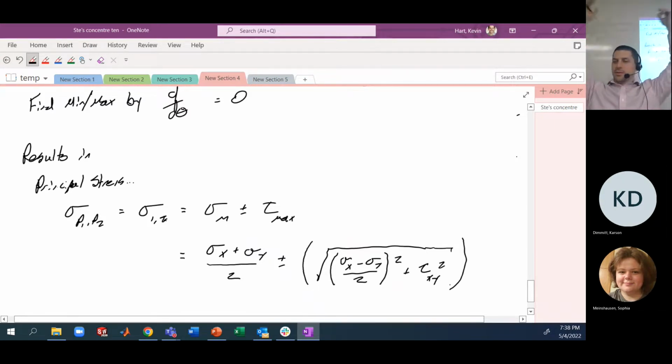Okay. Rotation angles that you need to get to principal stresses and maximum shear stress, they're also gotten from this derivation. Looks like 1/2 tangent inverse 2 tau xy over sigma x minus sigma y if you're doing principal stress. And the shear would be similar to that, 1/2 tangent inverse of sigma y minus sigma x over 2 tau xy, I think is what it is. Yeah, okay. Those ones are hard to keep straight in your head, but somehow I stare at them long enough.